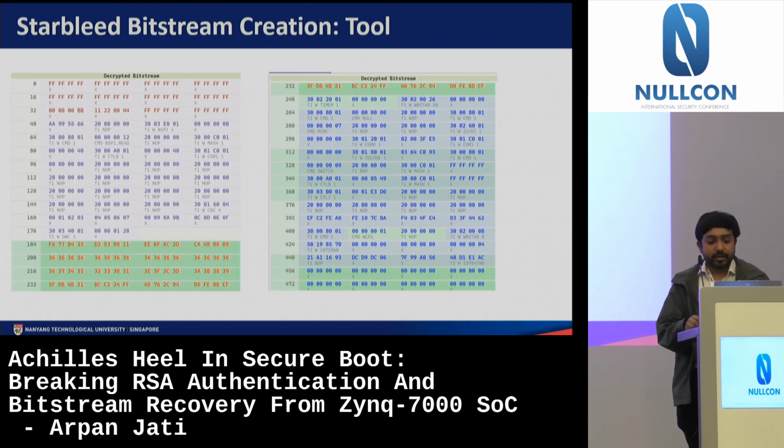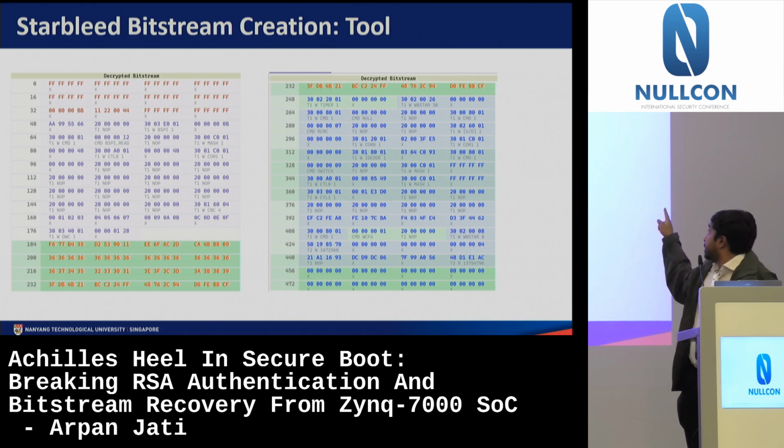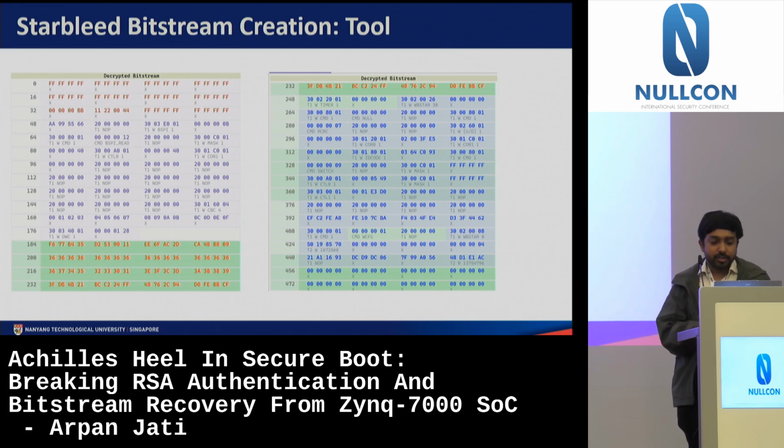So I can have a list of fault items where I can set a value. Okay, byte number 76 is being written with some XYZ value. That value will be XORed with the input. And using that, on the top right side, you can see the WBSTAR 38. That means the next 38 bytes of the image, or the encrypted part, are to be consumed by the WBSTAR command.